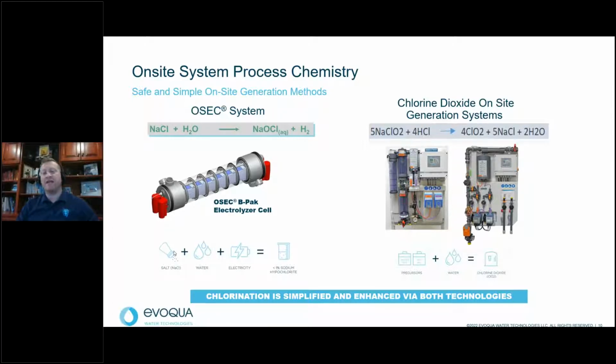This is really ideal for direct dosing or batch processes and leverages dilute chemicals for small and medium scale applications. The systems that we see have great success leveraging about a 7.5% sodium chlorite concentration with a 9% hydrochloric acid concentration, which is really perfect for these small scale applications in the beverage industry.